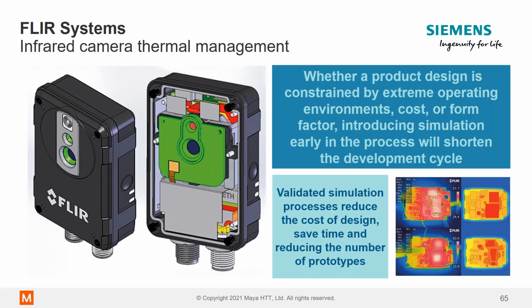And what you can see is a plastic clamshell. This is IP protected, so there's no fans, there's no airflow allowed through here. There's only the natural convection within the box, which can be used to cool the electronics. And we were seeing very good correlation between physical test, in this case IR from FLIR, versus FlowTherm simulation. So they were seeing great correlation in the upfront design stage. Next slide, please.